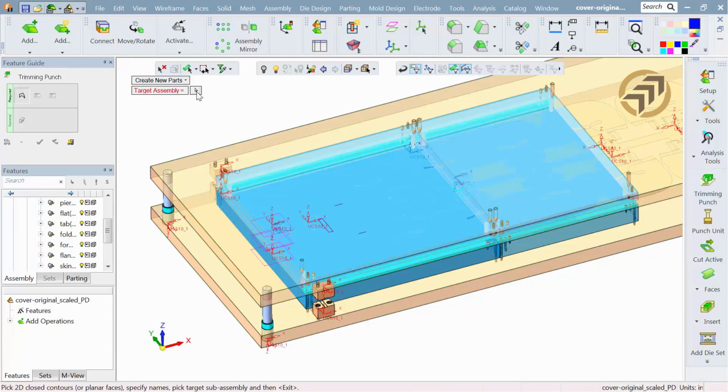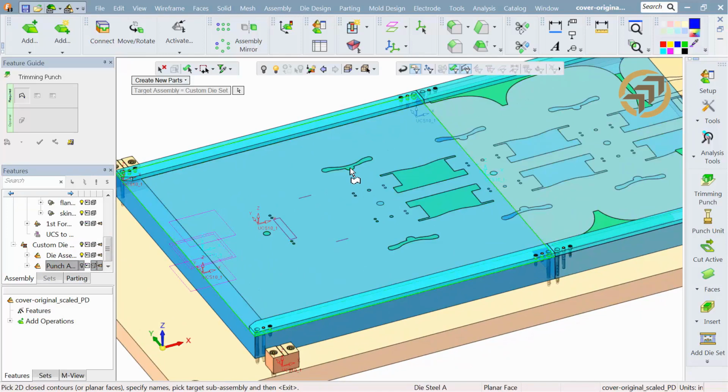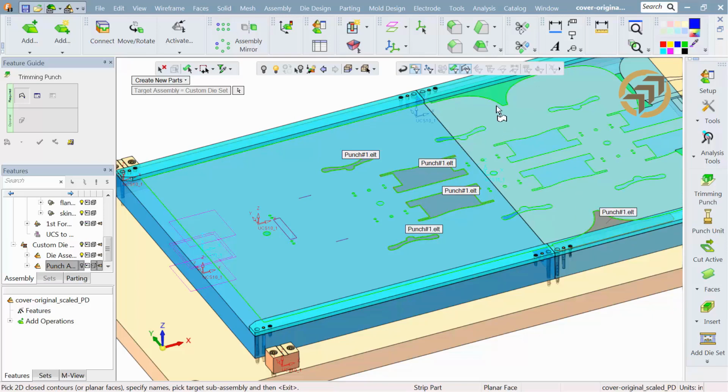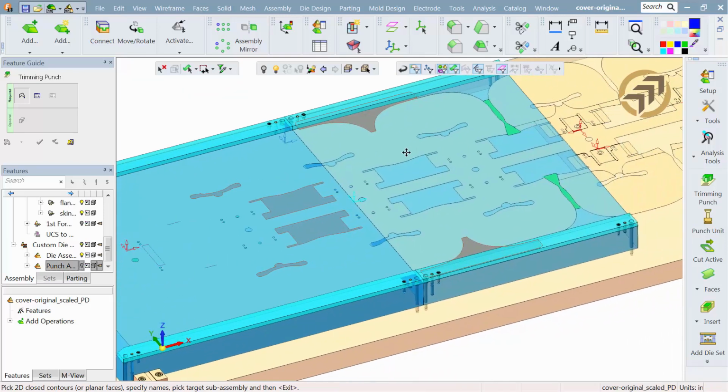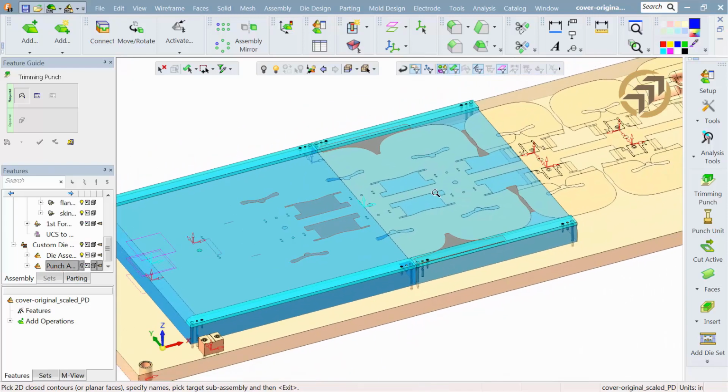So what we're going to do now is pull all the punches. And like I said before, you can use the punch geometry and mirror it, rotate it 180 degrees if it's going to be used again and again. That's fine. But for what we're doing here and to illustrate this functionality, we'll use all those punches that we have on the strip, and in one operation we'll create these punches and all the holes that they sit in. So focusing here on the wire EDM punches.